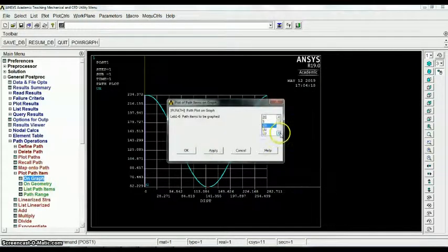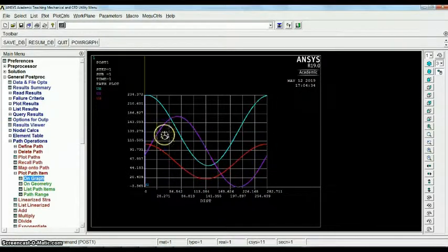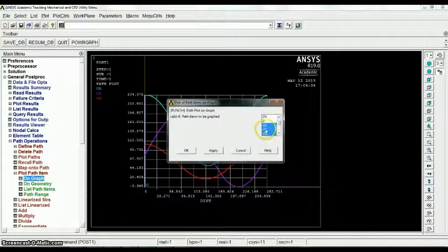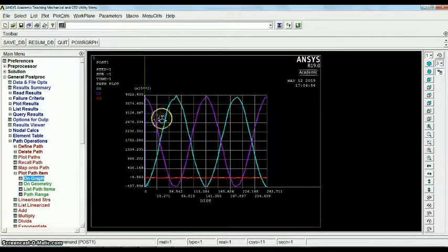Where you can see the X, Y, Z deformation all together. You can see, and as regular actually in X direction the maximum values, then Y values and minimum in Z direction. Deselect the deformation and select the stresses in X direction, Y direction, Z direction. So you can see here almost same as X and Y, the stress values, while in Z direction it is in minus. Minus stress means compression, not tension.